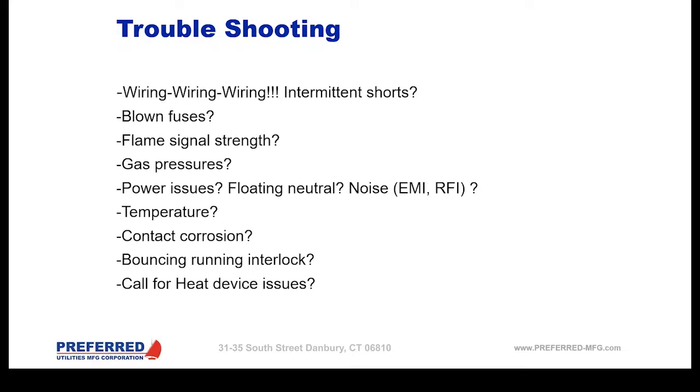Now, if you get out there and certain things are not operating, period, there could be blown fuses. So once again, when it comes to troubleshooting, the simple things are the things to start with. The wiring, blown fuses. Is it starting? Do we see the pilot? What's the flame signal strength?